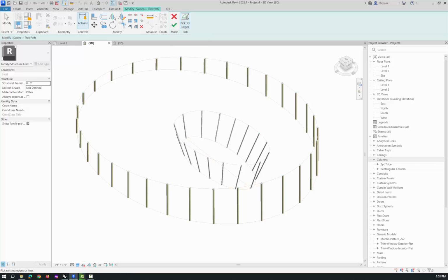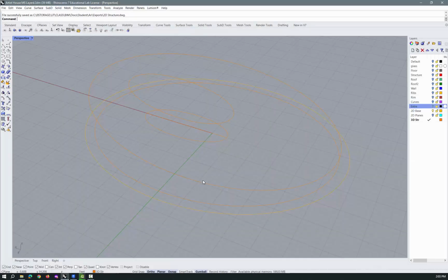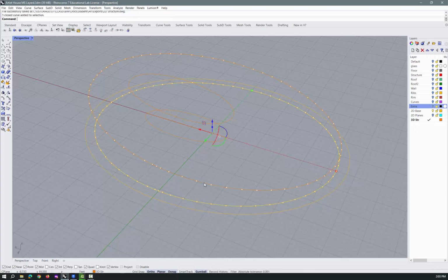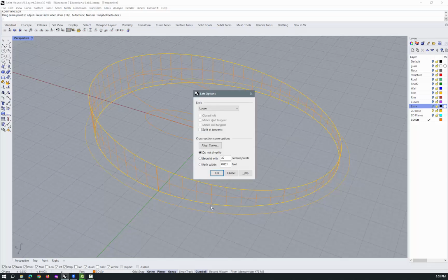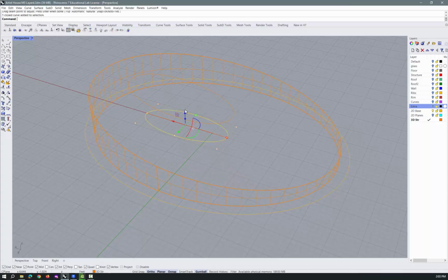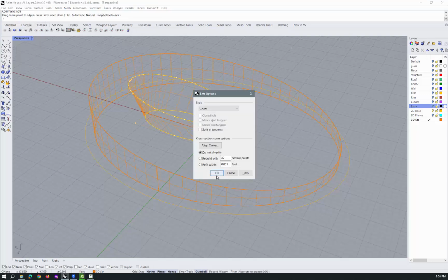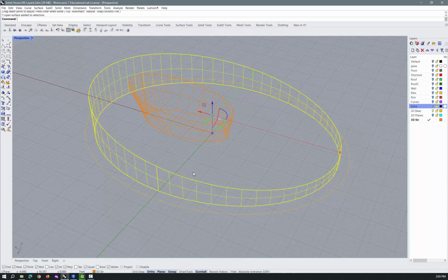Okay, so if I go to Rhino, I guess you could just loft it. So if I pick these two guys and loft them, and I'll need the same for these two, so I'll pick those two and loft them. Click OK. Then let's grab these two and File, Export Selected.